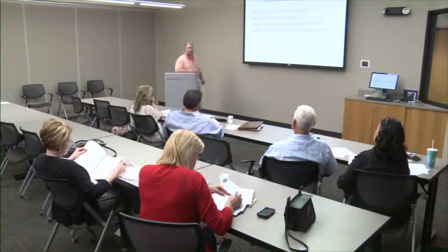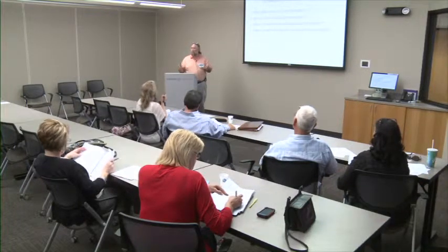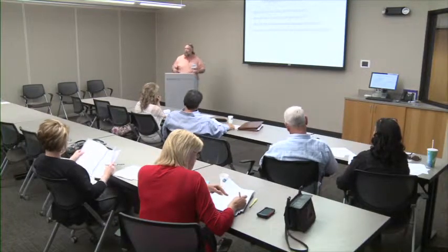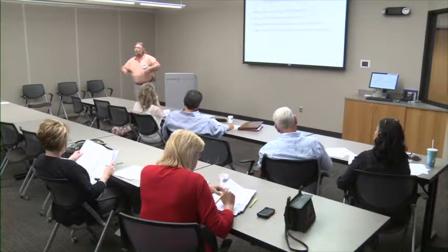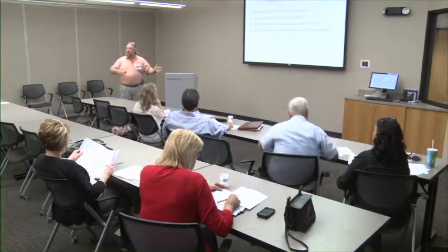It's important to know because each one of these schedules, when we implement it, we're talking about a baseline. We have a start point, what everything looks like to begin with. That's what we're talking about with a baseline schedule. And then as we start to monitor it, that baseline changes. So if I look at it 2 weeks after I started, the original baseline is no good anymore. I'm actually looking at a new baseline at 2 weeks. So what your baseline is and what you're looking at makes a difference.